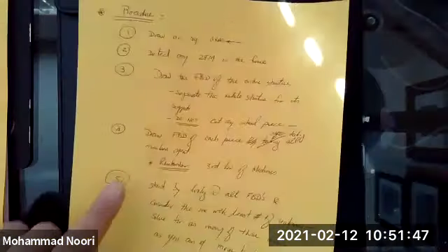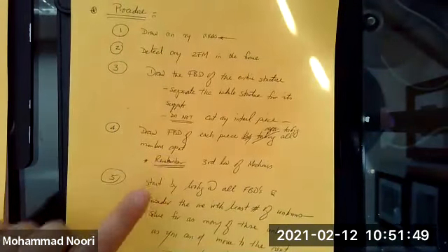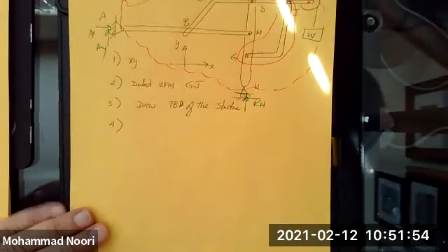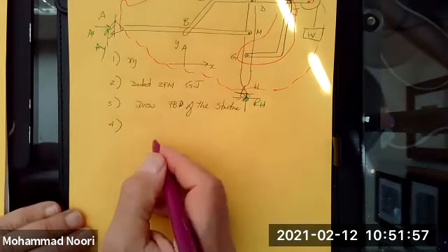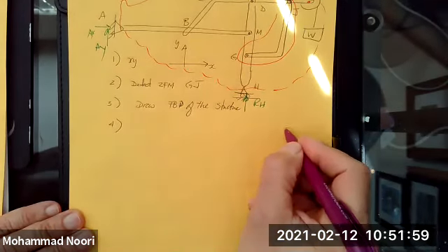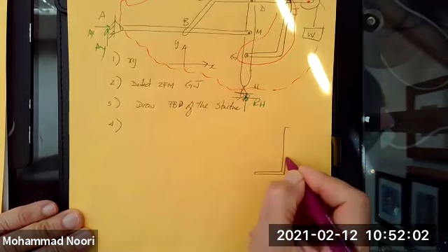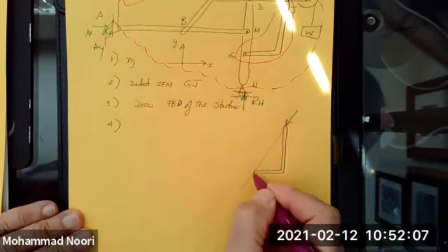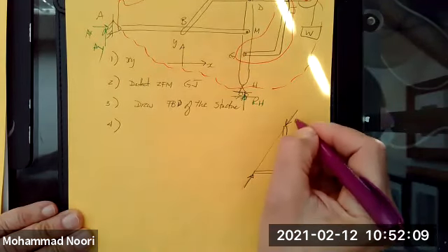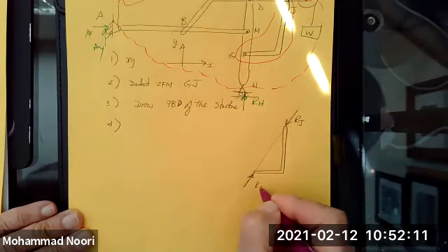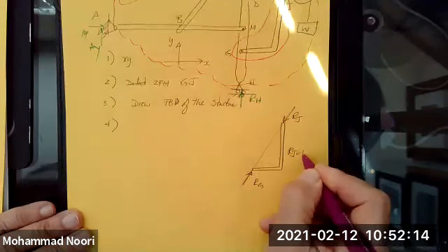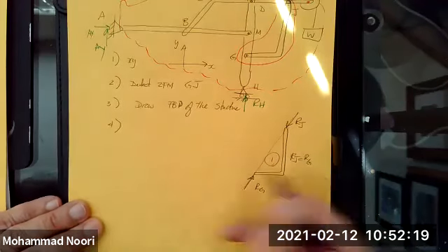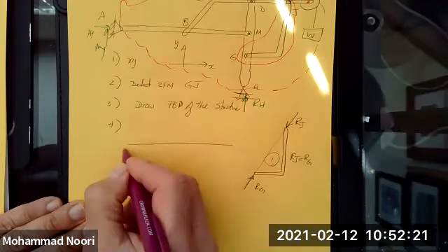Step 4, draw the free body diagram of each piece, okay? And remember the third law of mechanics. So I had this two-force member. Let me start with that one. So for the free body diagram, let's say I assume forces RJ and RG, which are of course equal, acting like this. So this is free body diagram 1. Let's look at this member,